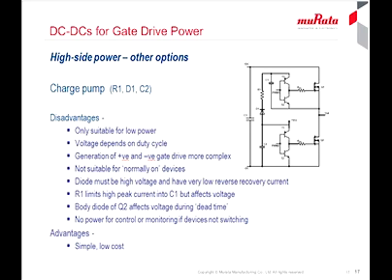It only generates a positive rail, so the gate cannot be driven negative unless further circuitry is added. The components must also be chosen very carefully. For example, D1 has to be a high voltage diode with very low reverse recovery, and R1 is needed to limit peak current into C1, which then reduces the accuracy of the voltage even further.